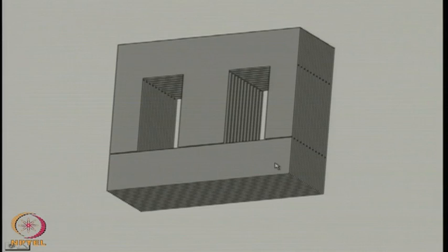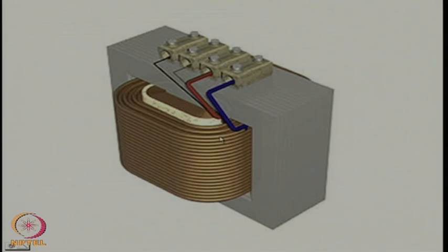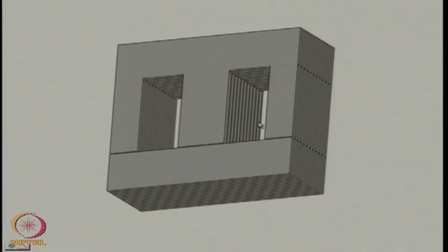The transformers are laminated in order to reduce the eddy current loss. Now, you are all familiar with the mechanism of eddy current loss. If there is a coil which produces an alternating flux, the flux flows through different parts of the core. Since this is an alternating flux, it produces circulating current around them.